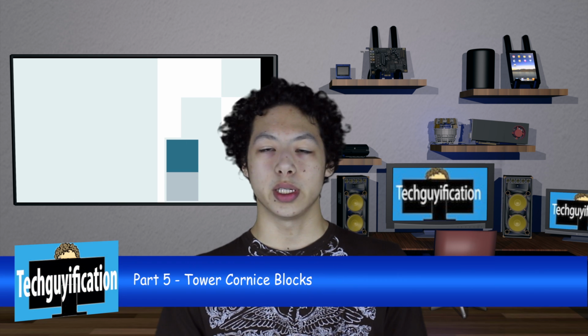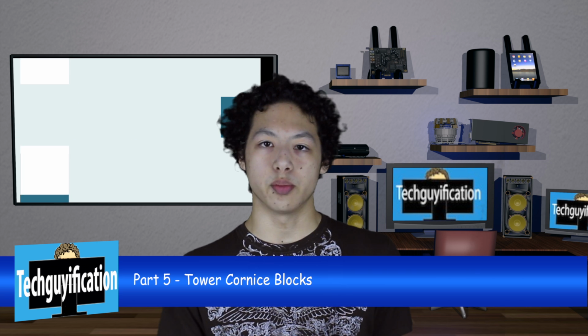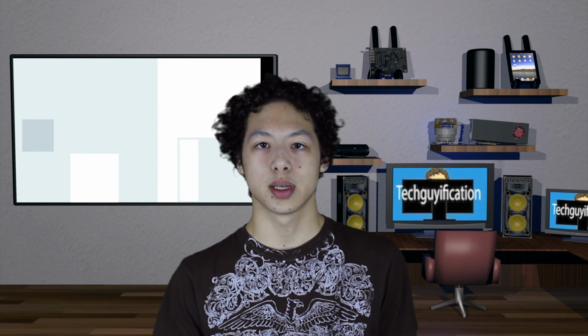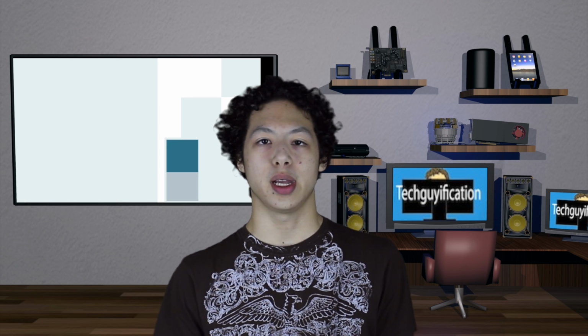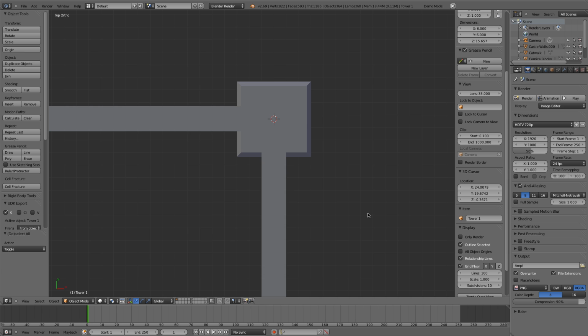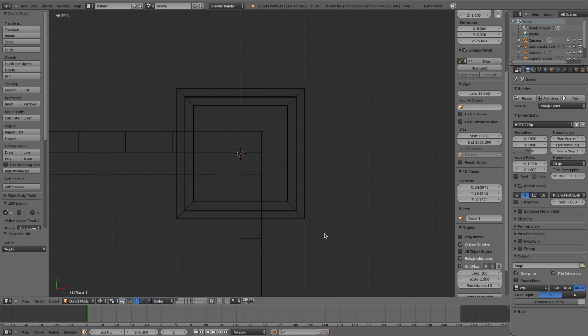So now we're going to do the tower cornice blocks. We're not actually going to do it the same way that we made the previous castle cornice blocks, because I want to show you a different way of making them. So now go into top view by pressing numpad 7 on the keyboard, and then press Z to go into wireframe view. Now you can zoom in a bit on the tower by scrolling in with the mouse wheel, and then press Shift and hold down the middle mouse button so you can pan around to adjust your display.